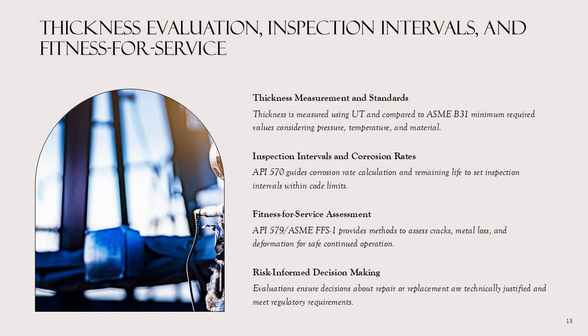When measured thickness approaches or falls below acceptable limits, inspectors must evaluate the piping's fitness for continued service. Fitness for service assessments, often performed in accordance with API 579/ASME FFS-1, provide a structured methodology to assess the acceptability of flaws such as metal loss, cracking, or deformation. These assessments support informed decisions on whether piping can continue to operate safely, requires repair, or must be replaced. Proper evaluation ensures that decisions are technically justified, risk-informed, and aligned with regulatory and company requirements.